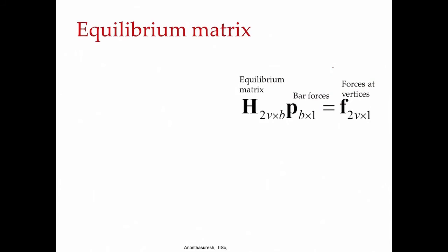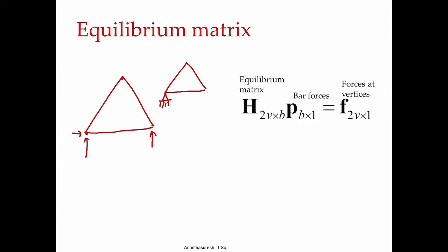Now, let us understand a computational method for identifying special geometries as well, and for that, whatever I just wrote there, if I have a truss, I want to write the equilibrium equation at each vertex. Let us say I take this vertex, let us say there are ground reactions like that, meaning that our truss is fixed here, whereas here it is pinned and can slide, whereas this is just a pin. If I have such a thing, these are 3 reactions I have.